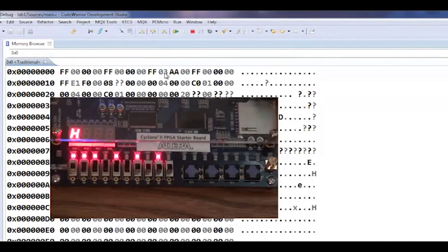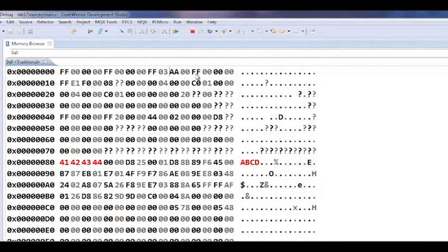So the only values you can put in here are 0, let's try 0, and you can see those are off. We can put in a 01, or we can put in a 02, but every time we type in these numbers, notice that it remembers these because these are read-write registers. So we can put in only values 0, 1, 2, or 3 in here, and so these addresses, 9 and A rather, control the red LEDs. That's A, B, C, D.